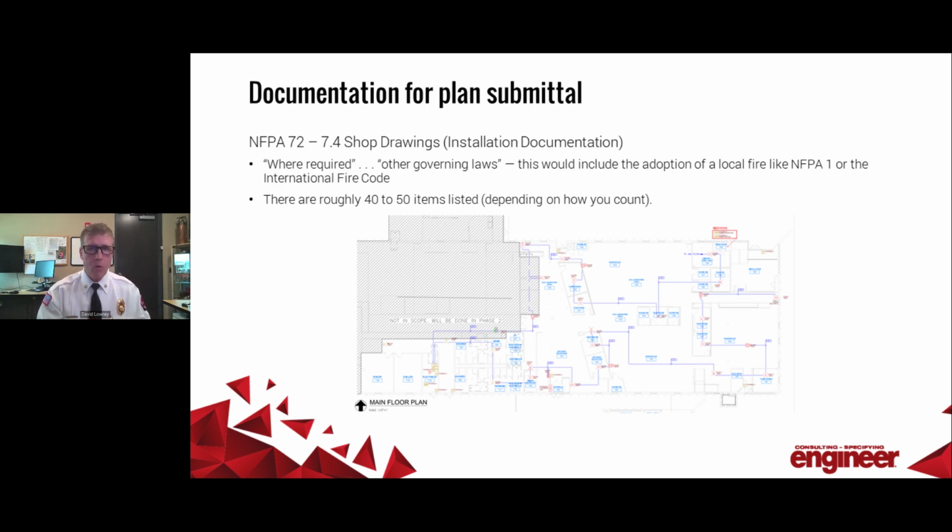Something like NFPA 1 or the International Fire Code mandates that you submit drawings for permit, right? And so when you look in section 7.4, then you run through approximately 40 to 50 items that you have to include on those shop drawings, depending on how you count, between sub-bullets and not sub-bullets, which is the reason I put that rough number in there.